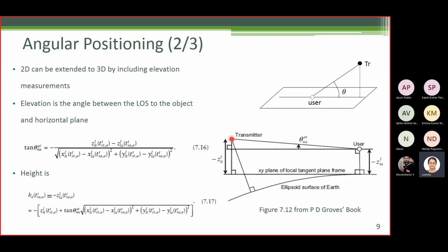In case of VOR or TACAN, the base station coordinates will be known once the aircraft receives signals. There will be some signature in the signal that will tell the aircraft which base station it is, and base station coordinates would be known a priori. So let's assume that the transmitter coordinates are known.